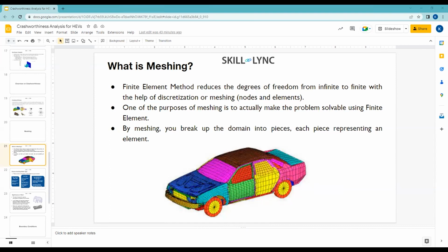Young's modulus, let this be Y. And your strain is what? Engineering strain is your change in dimension divided by initial dimension, so delta L by L. Now suppose F was equal to kx. If I want to represent F from this equation, I can represent it using F equals YA delta L by L.